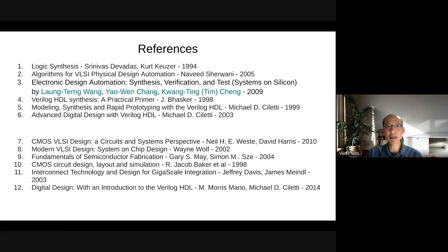You might not get much about it, it's called a layout design, but you can see that the book is about physical design. In that, the first step is you have to do the floor plan, you have to do the placement, and you have to do the CTS, which is clock tree synthesis, which is very basic and fundamental to physical design. And later you have to do the routing and post-route optimization after routing.